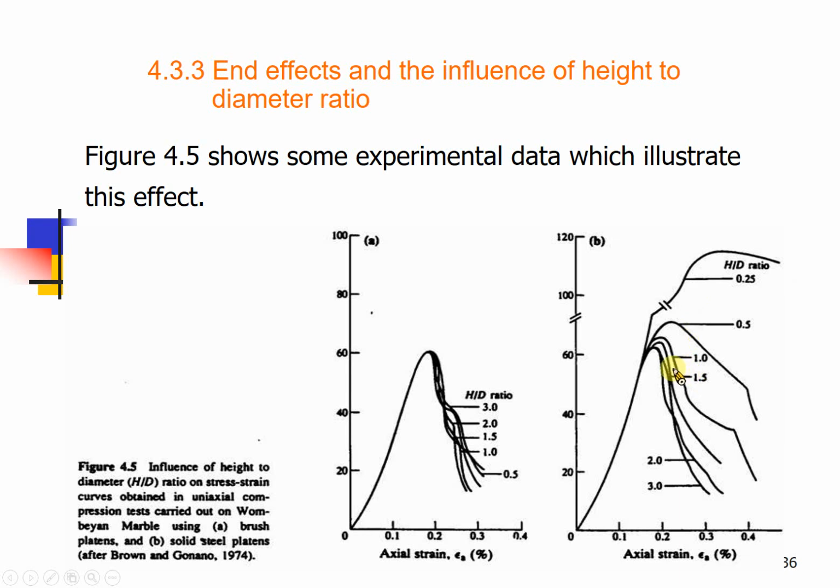If we try to eliminate the end effect using the so-called brush platen, we will have a lot of needles. If we apply the load with a lot of needles, can you understand? If the needles are very stiff, when you apply load, the load will be applied like this, not like this, but like this.